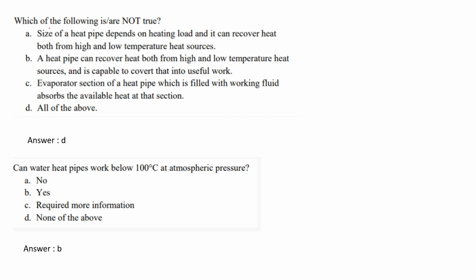Okay, and the heat pipe envelope will be made of copper. If you are giving a maximum of 150 degrees Celsius, the saturated water vapor pressure in that copper envelope will be around 477 kilopascal. So it will be okay for that heat pipe. So the maximum temperature you can give is 150 in the case of water and copper heat pipes.